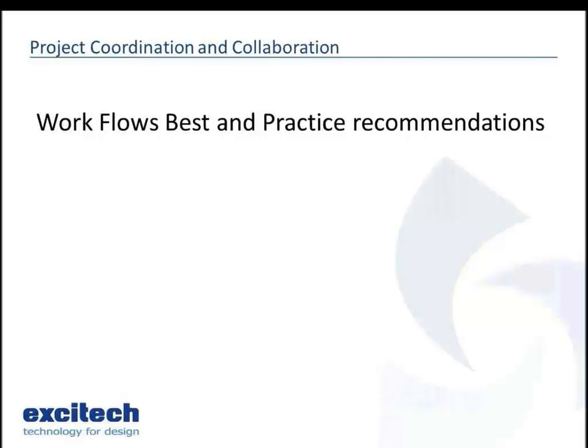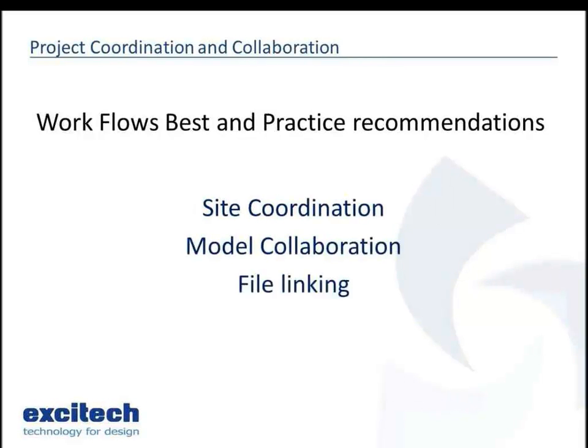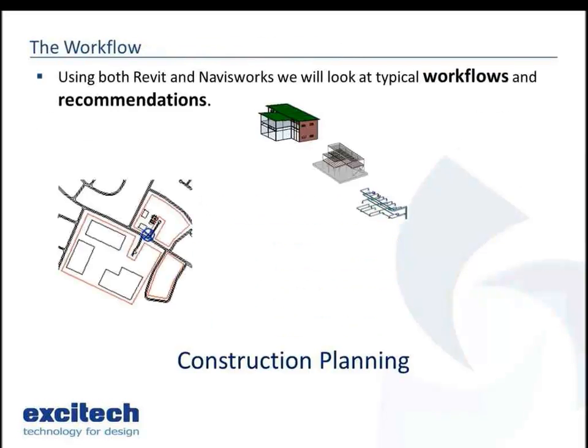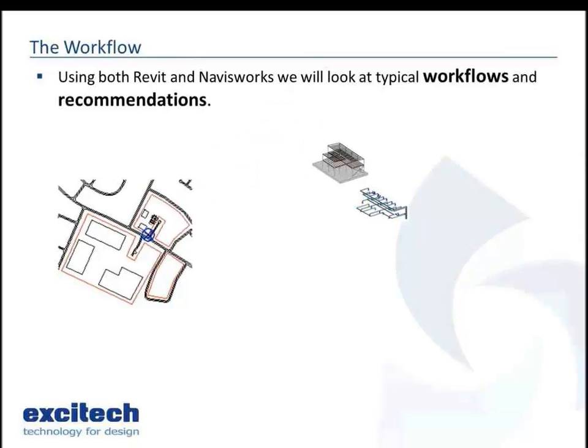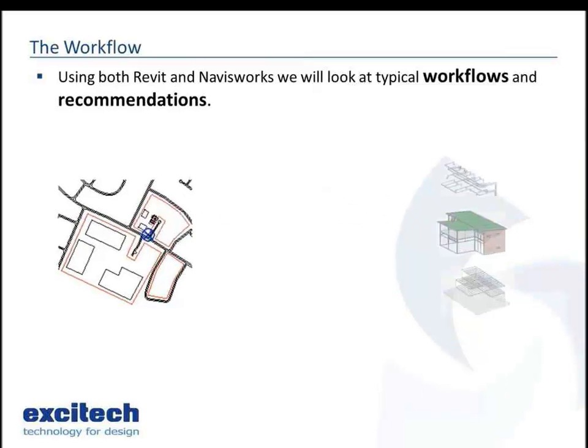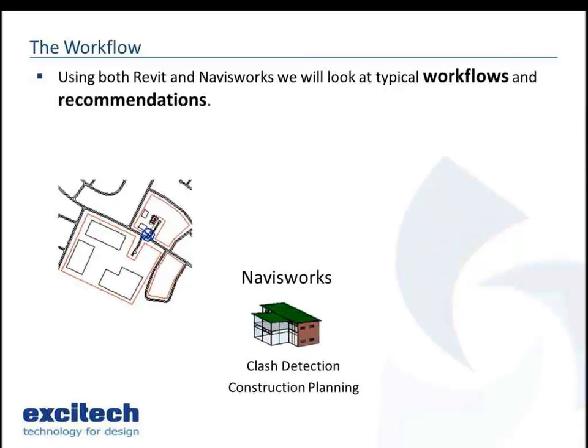During this session, we'll be looking at workflows and best practice recommendations. This will include subjects from site coordination and file linking to collaboration between disciplines, clash detection and construction simulation. Specifically, we'll consider setting up a site file, linking Revit models into the site, and then sharing the coordinates from the site back out to the linked files. Linking building models from multiple disciplines into one coordinated model, and continuing the workflow in Navisworks, where we will conduct clash detection and construction simulation.